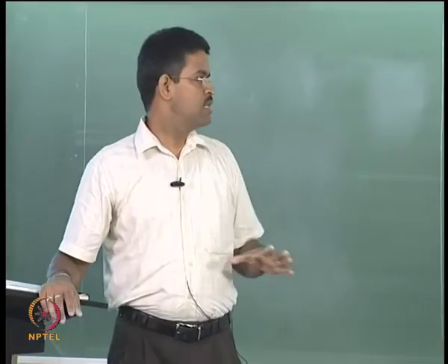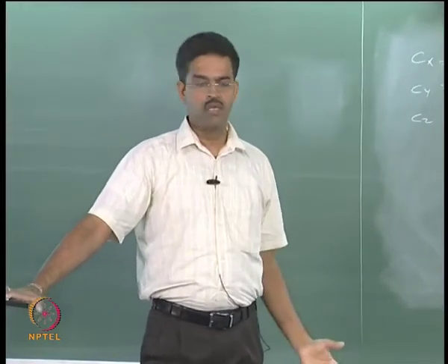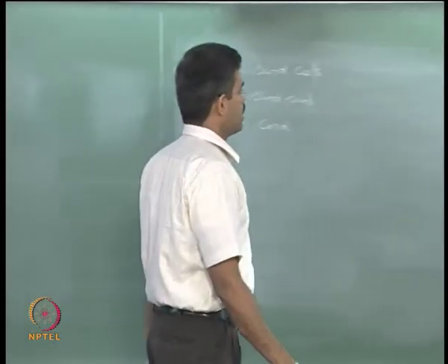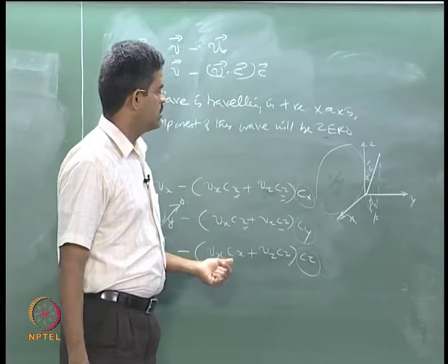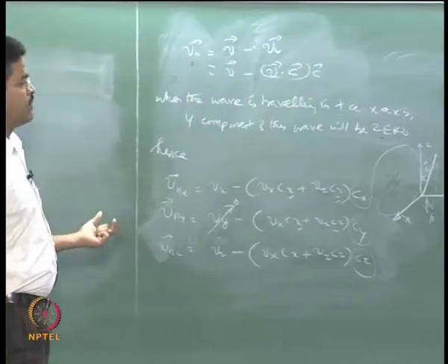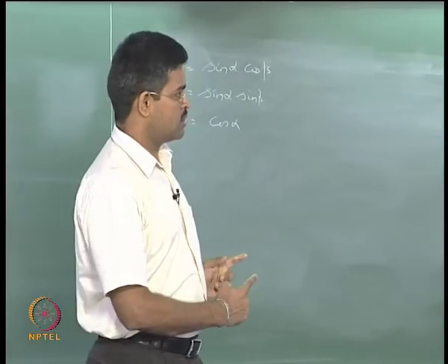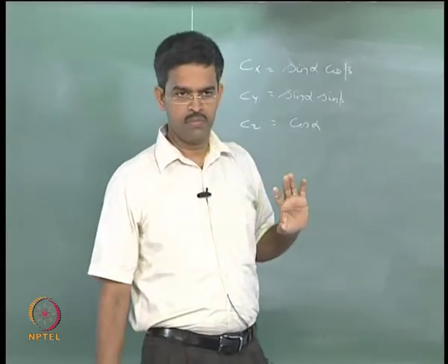So, f of t can be linearized, the drag nonlinearity can be taken away by an approximation as we just now showed. Similarly, any member which is arbitrarily oriented other than vertical or horizontal can also be handled in the same fashion. So, the wave force for unit length of the member, which is the right hand side of the equation of motion, can be sorted out by this.